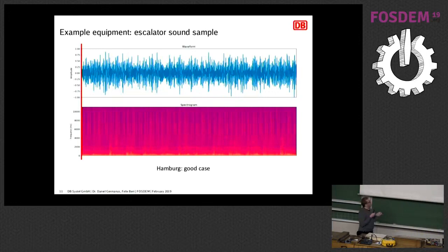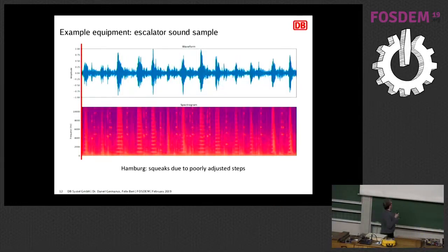Now I'm switching to a squeaky recording. So here the steps are not properly adjusted, and they make a very intensive noise, and also the ball bearings are actually suffering and tend to fail after some time if no maintenance personnel is about to fix that.